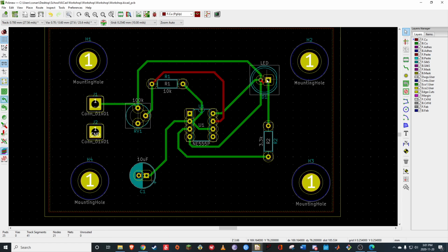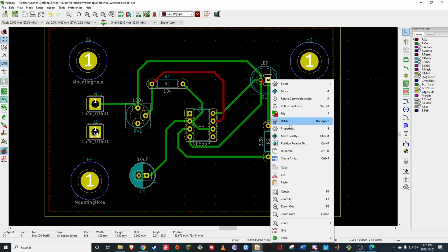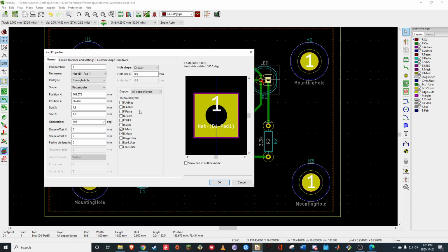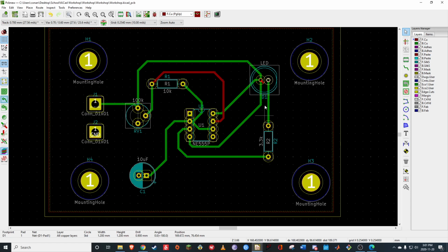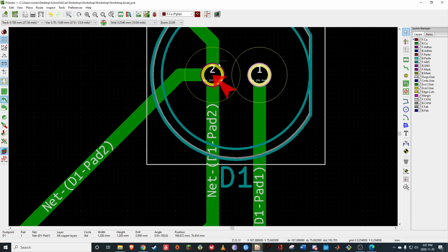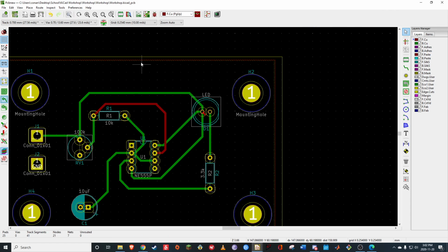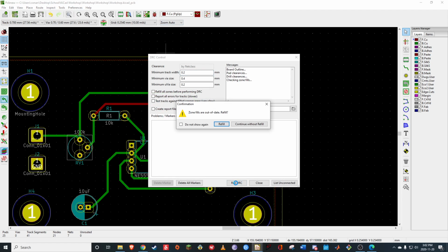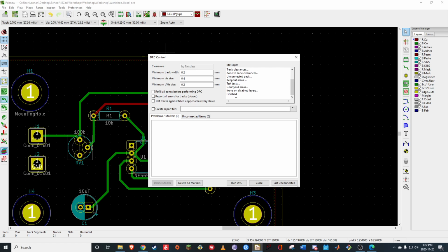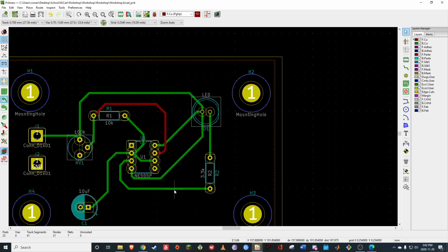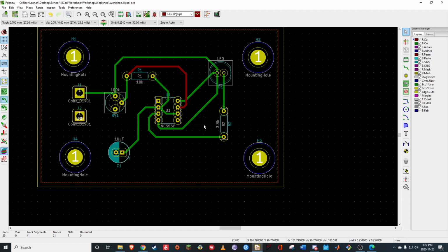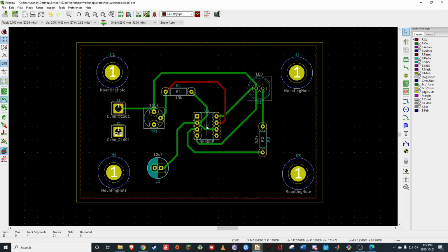and I make the diameter, well, first off, I turn this one into a circle as well, so change the shape to a circle and change its diameter to 1.2 as well. Now, this gives us enough copper that we could go in there and actually solder things to it, but it's also going to make it so that they have more than enough clearance between each other that running the debugger won't give us any errors. So now it's finished. So now, technically, this is a completed board.